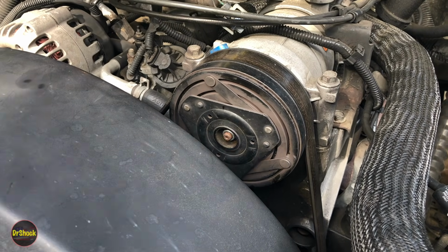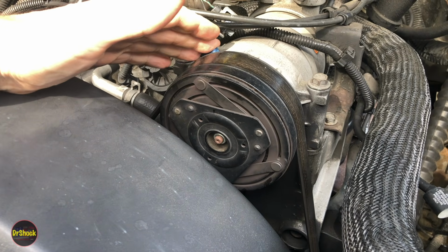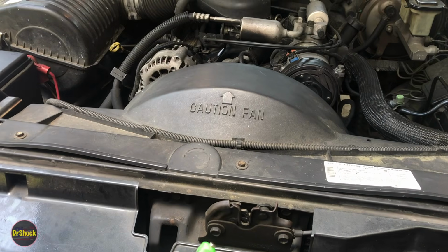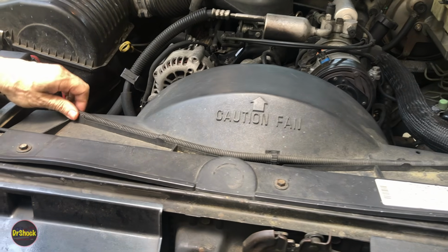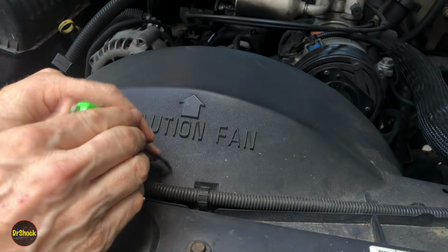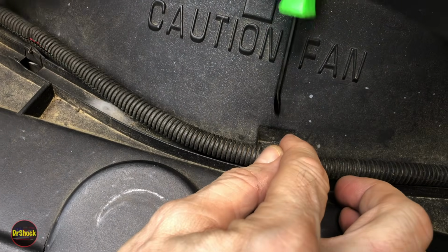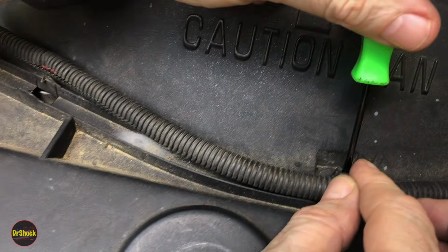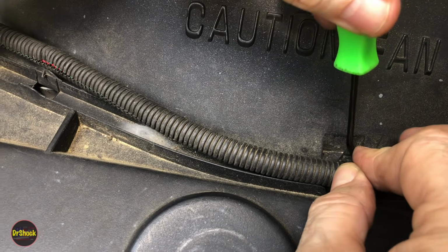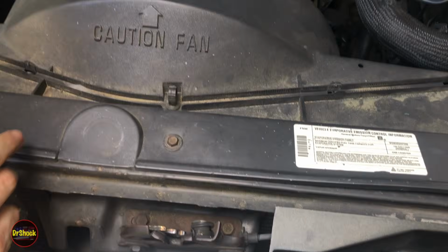Just to eliminate that variable, we will do that change, and let me show you the tool that's required to do that. All right, guys, I guess I'll go ahead and show you doing this air gap adjustment. So we're going to take this upper fan shroud off. Use a small prying apparatus or screwdriver to gently coax this clip off without breaking it. Stick that behind the upper